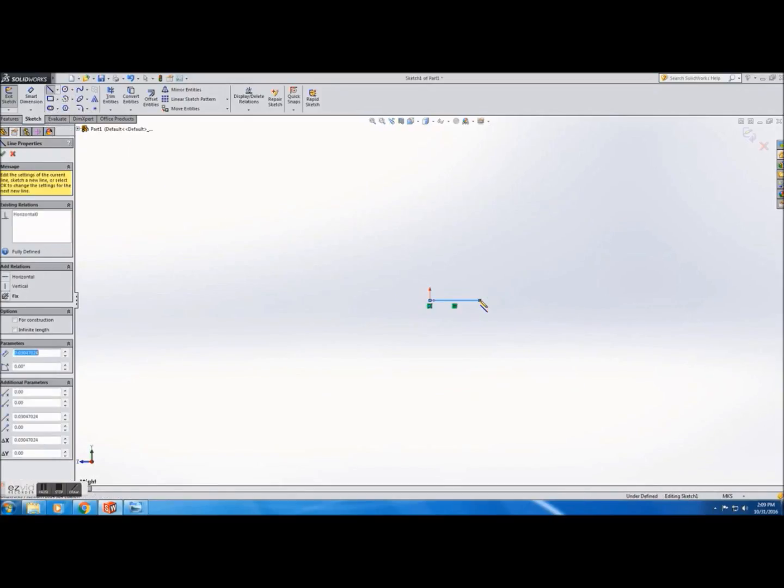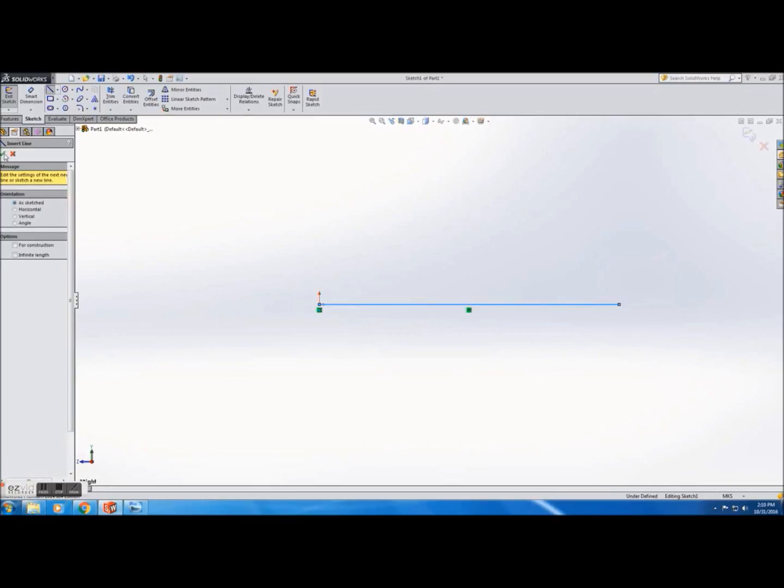Or if you've got a plane with a different set of dimensions, then naturally you're going to be using those, and if you want to be setting the plane to scale, you can still do that, just with your own personalized dimensions. So what you saw me doing just there was that I laid down a little line. This is going to be our length line, and I adjusted the length to be exactly that of the length of the plane. We're going to be using that to just line up our reference material.